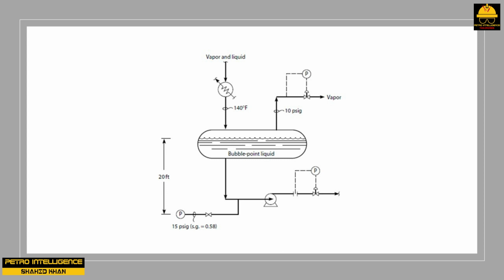The units of NPSH are feet of liquid head. The required NPSH of a pump is due primarily to the conversion of feet of head to velocity in the eye of the impeller. The available NPSH to a pump has the following definition: physical pressure at the pump suction minus vapor pressure of the liquid at the pump suction. To express the available NPSH in feet, measure the pump suction pressure and add the barometric pressure, 14.7 psia at